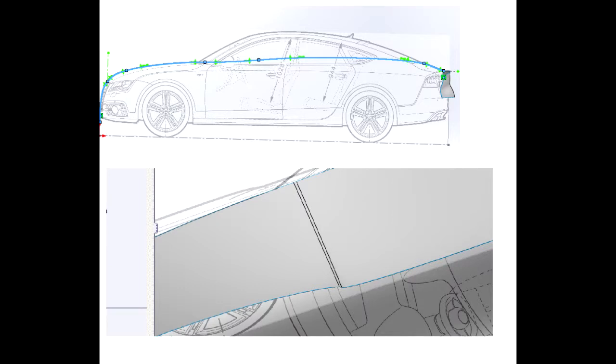Another issue I realized is that when I sketched with splines, it's better to limit the amount of splines used and instead just add more spline points to avoid breaks in your boundary surface.